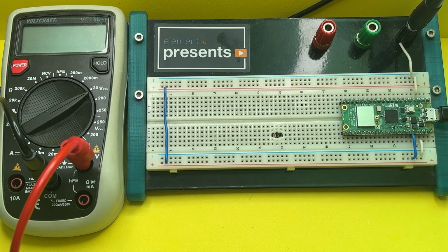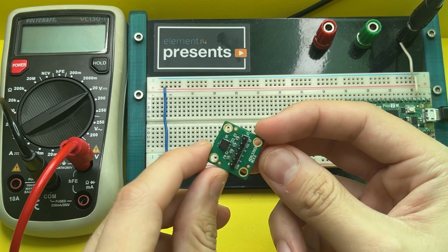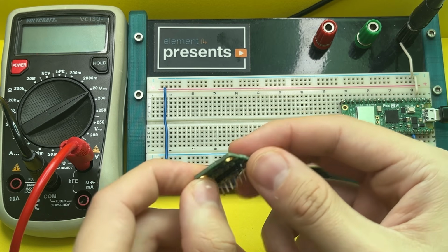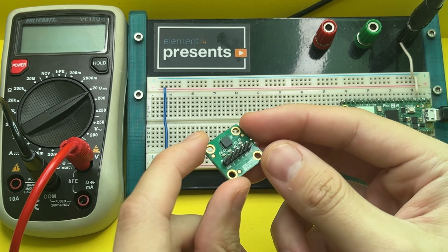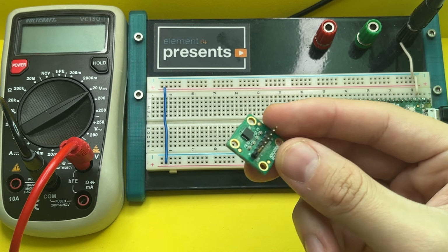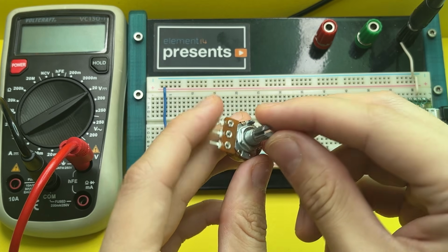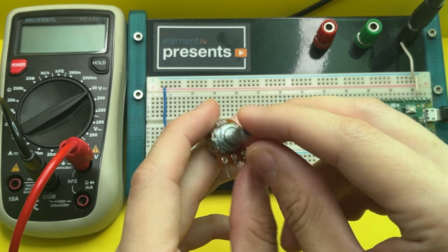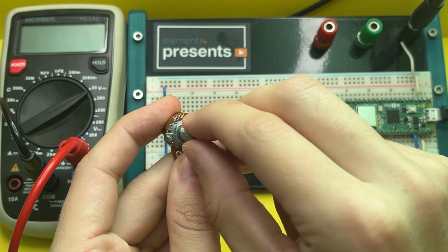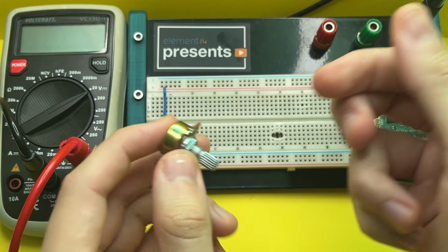Now we're at the bench and we're going to discuss sensors. When we say sensor, you can imagine things like this. This is an IMU and it measures your angular velocity and accelerations, and it's a really useful sensor when trying to control something in the air like a drone, for example. But we're going to go much simpler just so you can get the concepts, and we're going to use a simple potentiometer. This is actually a rather nice sensor. If you get a linear potentiometer, what that means is that there is a linear characteristic between the angle of the knob of the potentiometer and the actual change in resistance.